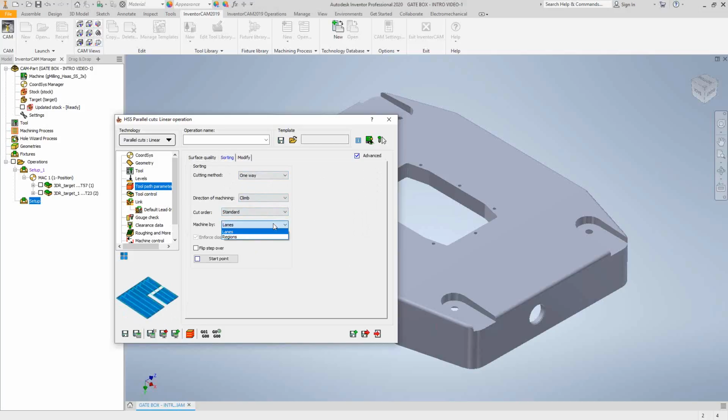If you look in the bottom left corner, right now we're doing lanes, so it continues the toolpath across any gaps. So you can select as many surfaces as you want. They don't even have to be touching, but just be aware that there will be air cuts there as it passes along there. Or we can set to regions, where it'll recognize that there's a gap there, and then just set this up into separate regions. And instead of jumping around in between these two, it'll do one and then jump to the other one. But in our case, let's leave that as lanes.